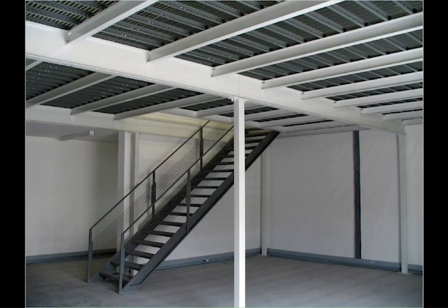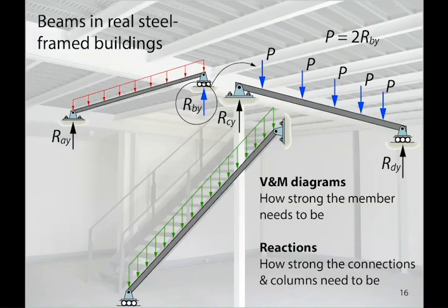All right, so each of those individual elements is something that you've already seen before. We've got some beams carrying uniformly distributed loads, one of the easiest cases to analyze of all the static problems that you've tackled. Those uniformly distributed loaded beams are going to sit on the girder, and those reactions from the joists are going to cause actions on the girders. You've got a series of point loads on a beam. You should be able to draw the shear and bending moment diagram for that case, and you should be able to calculate what the deflections of those beams are going to be vertically.